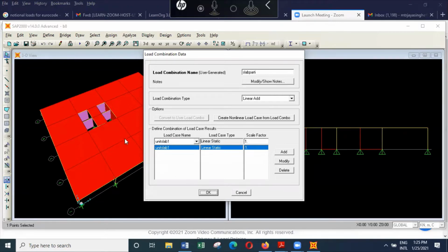So again, you can see I have not allocated any partition load weight for this area. I have done this just to show you that in a building, you can use different unit load values, and in some areas you don't have to add all the loads. You have to add those loads only if they are applicable. So here you can see unit load 2, I'm not having any partition load because it's a passage where people are able to gather.